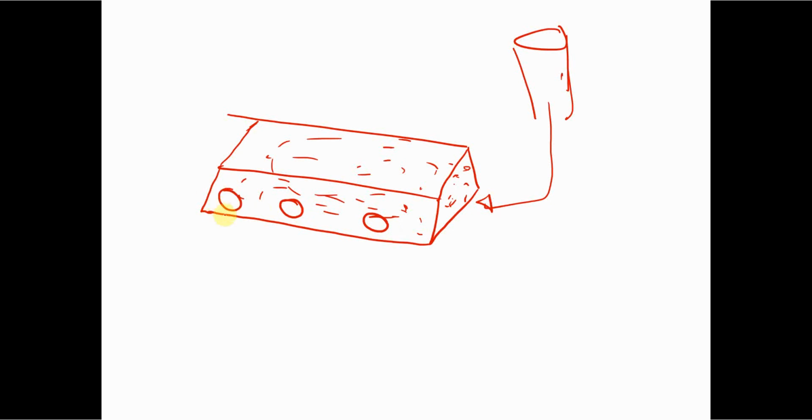All of these openings are the gates, or we can call them ingates, as we agreed, right? Since all of these gates should be located very close to the base, this distance should be very small, or they should even be opened directly over the base.